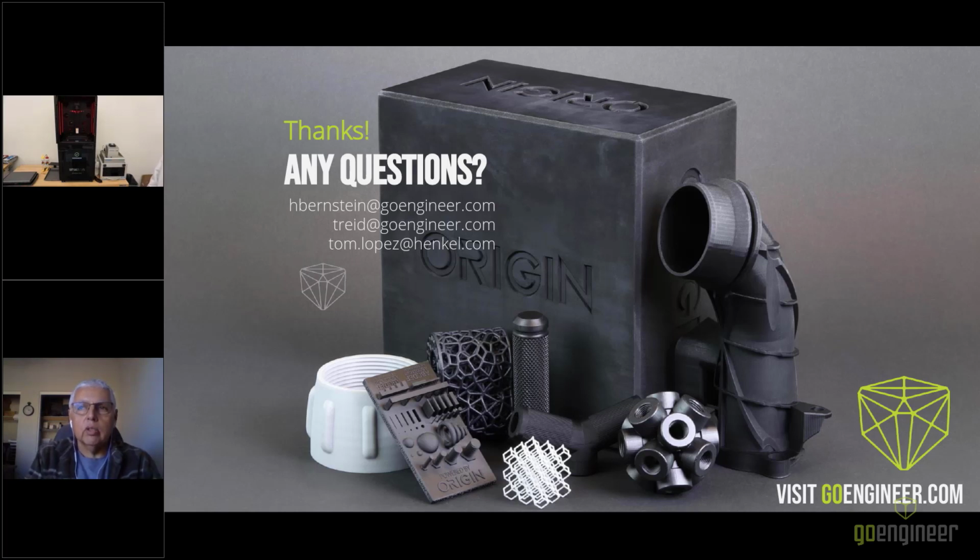And then post-curing, with the right intensity of light at the right wavelength. When you print a resin, it's printing really just green handling strength. When it comes off the build plate, it's going to need cleaning and additional curing in a UV system to achieve its final properties. So there is post-processing that is required.